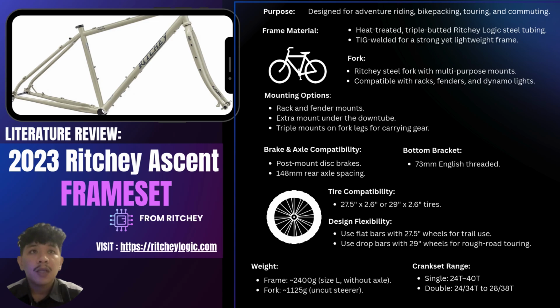For the mounting options, it uses rack and fender mounts, an extra mount under the down tube, and triple mounts on the fork legs for carrying gear. For the brake and axle compatibility, it has post-mounted disc brakes and uses 148 mm rear axle spacing. For the bottom bracket, it uses 73 mm English threaded, and the tire compatibility is 27.5 inches by 2.6 inches or 29 inches by 2.6 inches tires.